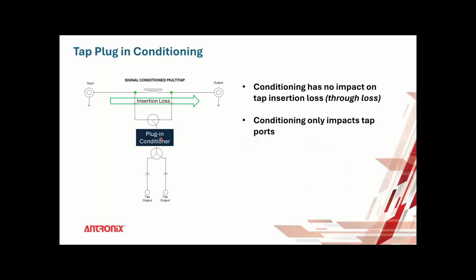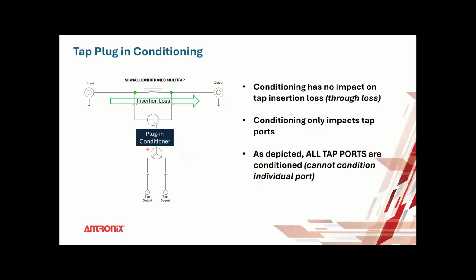This conditioner only impacts the tap ports. So if I put a cable equalizer here, the tap ports will be equalized, not the through line. And as depicted, all tap ports are conditioned. You cannot condition an individual port with this plug-in conditioner. So whatever I put here is split into two, so it affects both tap ports in this example of a two-way tap, two-port tap.